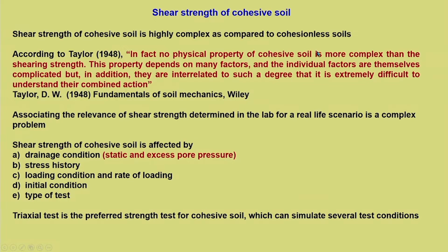and use as a fundamental property. Now, just like the direct shear test that we used for explaining shear strength of cohesionless soil, we will use typical triaxial conditions or triaxial testing for cohesive soil, because you need control of 2-3 factors, specifically drainage, pore water pressure measurement, and so on, because these are important factors as you could see.